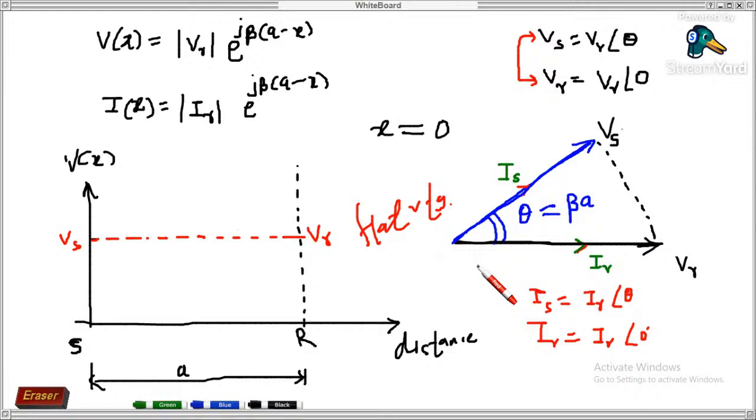This is called a flat voltage profile. This is possible only if the line is loaded at natural load. Apart from this, suppose you do not load your line at natural or surge impedance loading, something is different. Let P be the actual loading of the line, and P0 is the surge impedance loading, SIL.